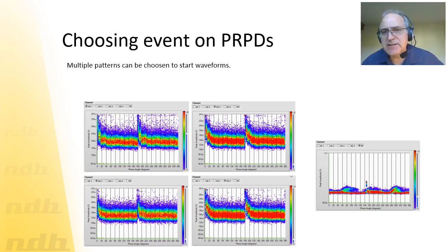This is a real example. The same example as the one that has multiple ground straps. A real case. Which channel are we going to set the triggers on? That's a good question, and there is no bad answer. You see on the right, on the electric, to me, it was suspicious, 3 bumpy things, and on the left, on the acoustic, they look similar, but there are 2 events per cycle, so they are also suspicious.